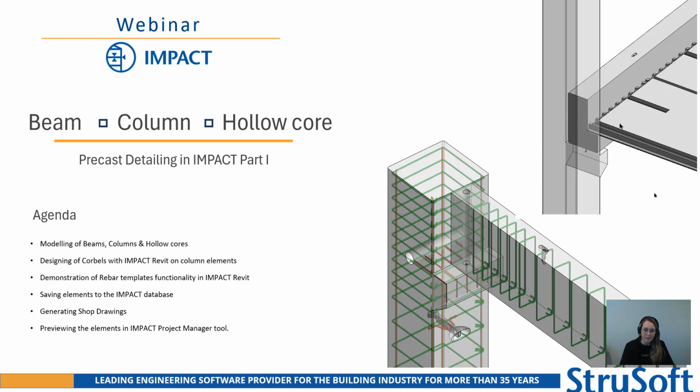Once we're done with the modeling, we're going to save the elements and generate shop drawings. Again, here we're going to use a shop drawing template. I'm going to show you how, in a few seconds, you can have the front views, the sections, and the schedules that you've set up in your template and get some really presentable precast detailing of a shop drawing.